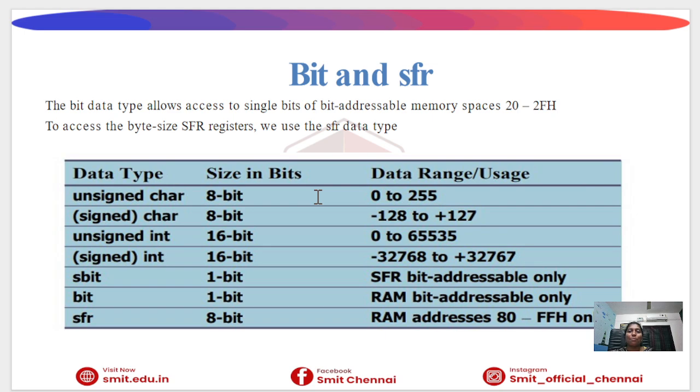Choosing the wrong data type may still work, but it becomes bad embedded design. There is also an impact on the hex file size, which becomes higher and higher. The char compiler generates fewer instructions, whereas using int unnecessarily means the compiler needs extra instructions to handle 16-bit operations. As a result, it produces a larger hex file and slower execution. So data type selection is very important.